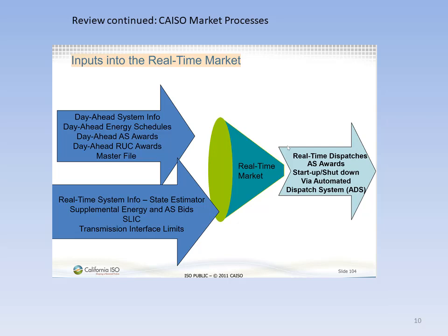For real-time dispatch, RTD, the time horizon is every 5 minutes. Generation units aren't committed on this horizon. There exists a special mode of RTD, real-time contingency dispatch, RTCD, that does involve ancillary services. Contingency-only reserves can be activated, and additional ancillary services can be procured. Note that RTD only enters RTCD after a grid event has occurred. More details are available in the real-time dispatch tutorial.